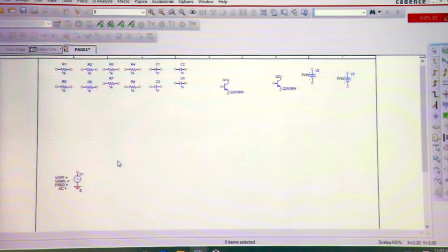And then from there, when you want to place wires, you press W on the keyboard, and it'll create this little cursor, so you have a little crosshair, and you can just click on connections and start drawing wires. And you can draw them wherever you want, hit escape to stop drawing, and then you can highlight and hit delete to get rid of them if you want to get rid of them.